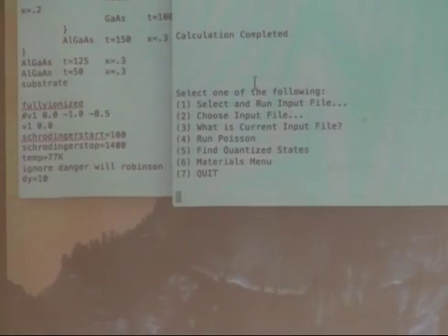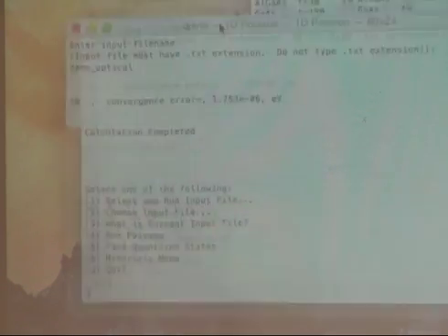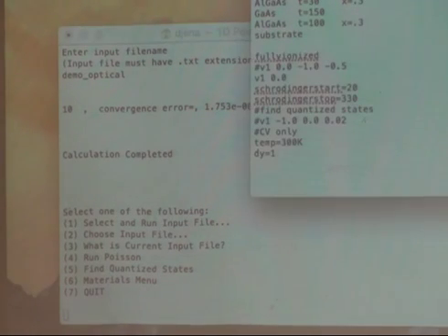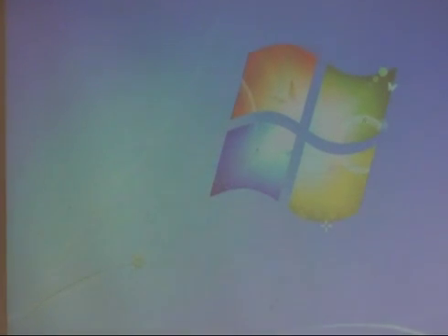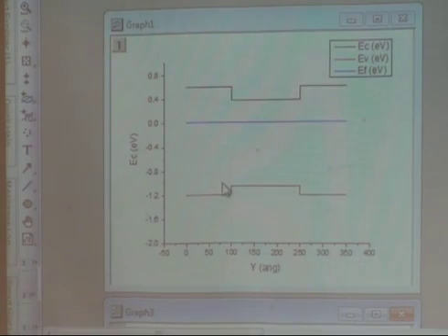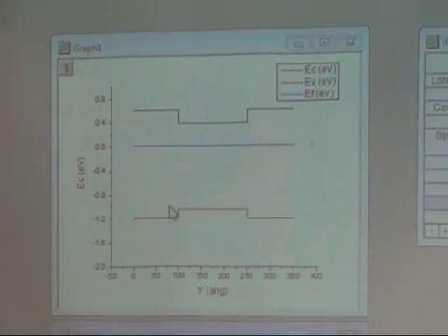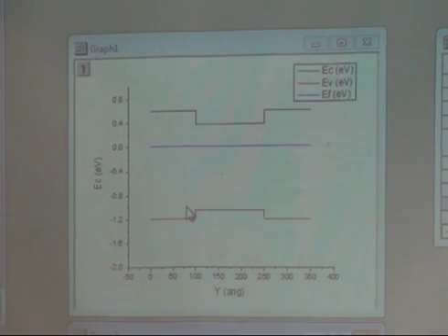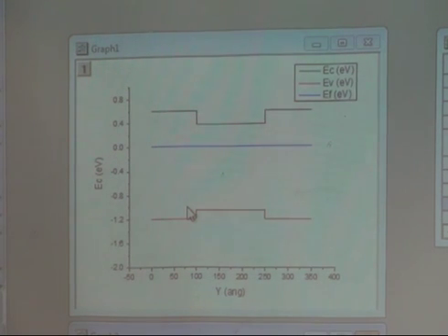now going back to the structure that we were looking at, the other structure we looked at last time, I think I'm done with that, was this quantum well, right? And what I've done here is, let's look at the quantum well. Okay, that's the one. Yeah, so you remember this one. And you can make it calculate each and every eigenvalue in the well. For electrons, it found, for example, in this problem, there are 4 bound states, and for holes, there are light holes, heavy holes, and it found bound states for all of them. Right, so you can find them. You can plot the wave functions of each of these states.